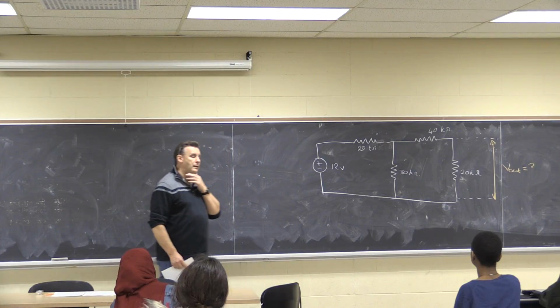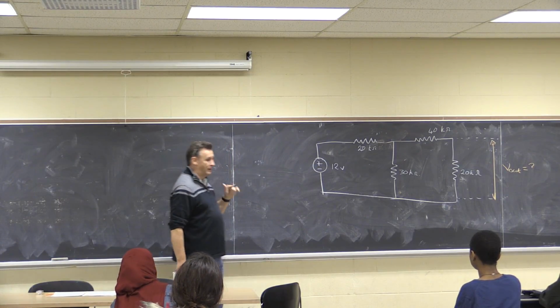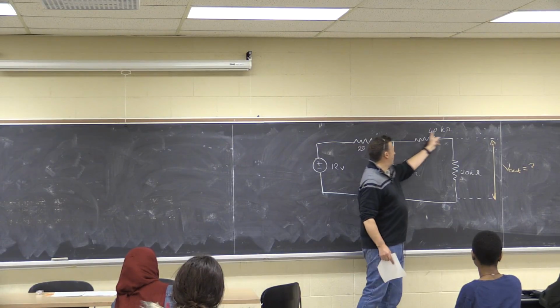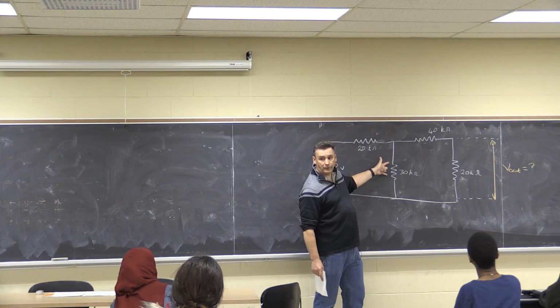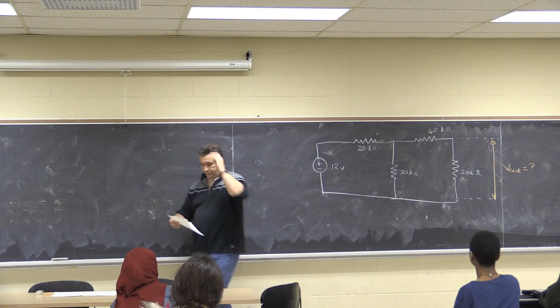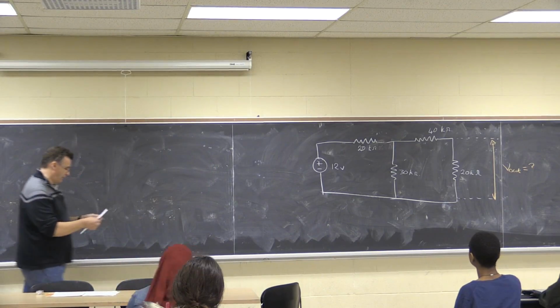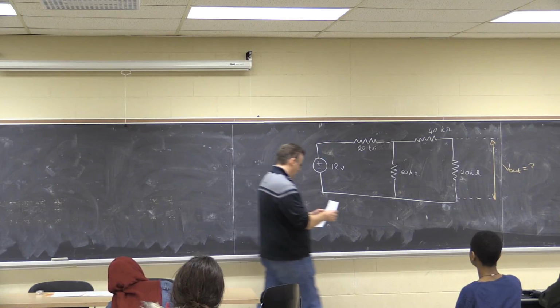What about equivalent resistance? Does that work? Yeah, well, in this one it does work because I can see these two are in series. This new one is in parallel with this one, and this combined one is in series with this one, so I could work out R equivalent. So this is a relatively straightforward one. So let's label these.